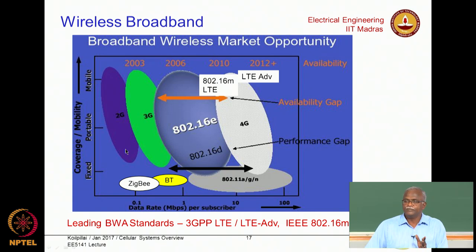and a little bit higher in the newer evolutions of Bluetooth. Compared to that, GSM or CDMA would give you coverage across a nation, basically a nationwide footprint. You could have full mobility, from low speed all the way to high speed on a fast moving car or train. So you have mobility and national coverage, but the data rates would be very modest: 9.6 kilobits per second. So it is very strong on the y dimension, not so strong on the x dimension. The cellular technologies said we need to fix this as the system evolves, because people are going to ask for higher and higher data rates, but we don't want to lose the advantage of mobility and wide area coverage. So from 2G to 3G to 4G, the curve is shifting to the right without compromising on mobility or coverage, while increasing the data rate.